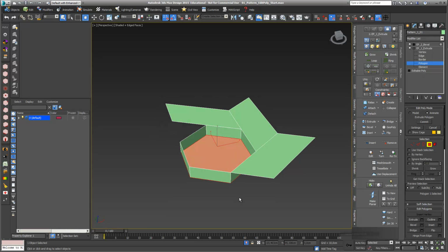So what quite often just happens with you, and you really have to be aware of and probably understand this, otherwise it drives you nuts. You really have to be aware that these Edit Polys rely on whatever kind of selection you did here. It could be even that you hold the Shift key and I just select several of them.